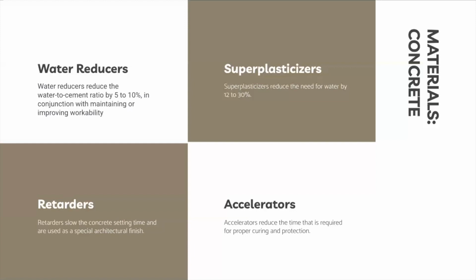Retarders slow the setting time, which is beneficial for intricate placements or special finishes, and counteract the effects of hot weather. Accelerators expedite finishing operations, which is particularly useful in precast settings and cold weather conditions, accelerating concrete setting and high early strength development while reducing curing time.